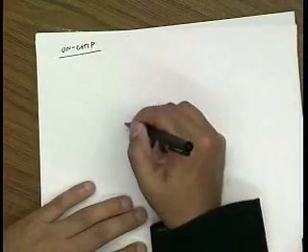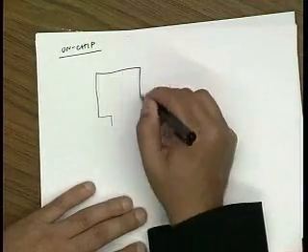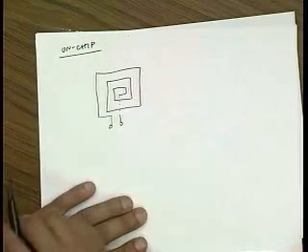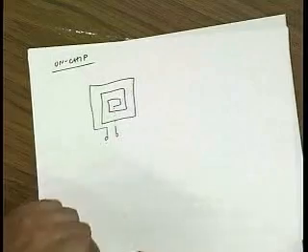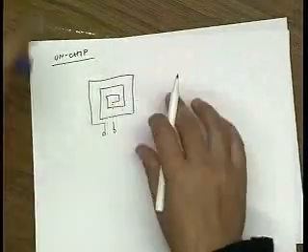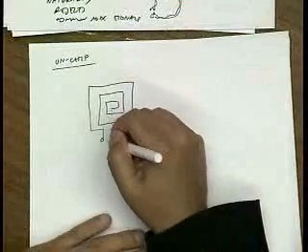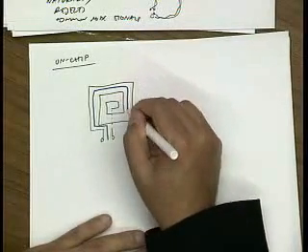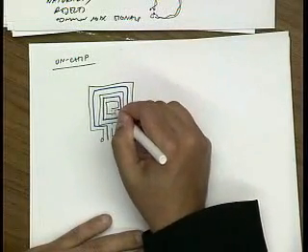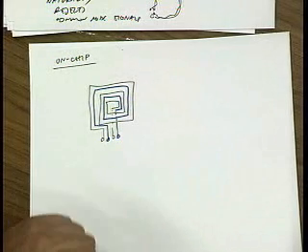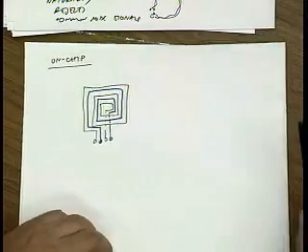And so the way you build an inductor on chip is you would just use a spiral inductor like this, right? So this is an inductor. One way to build a transformer is very much like this. I just wind a secondary around it. So this is a transformer. Or I could do something more symmetric.